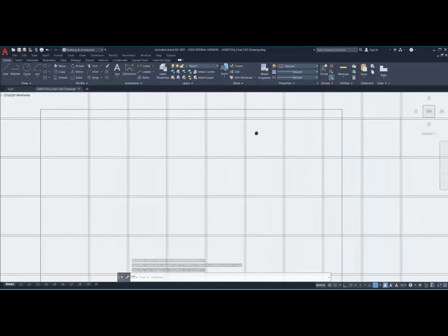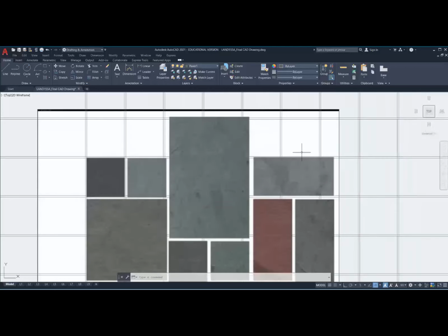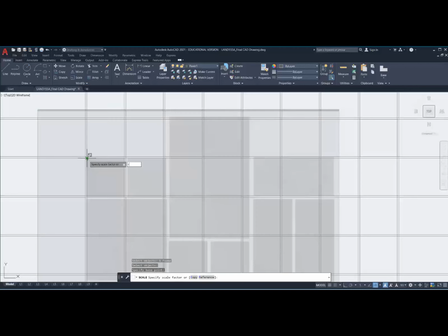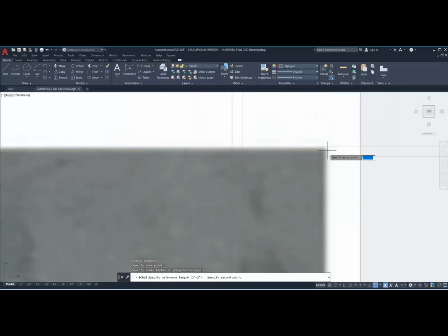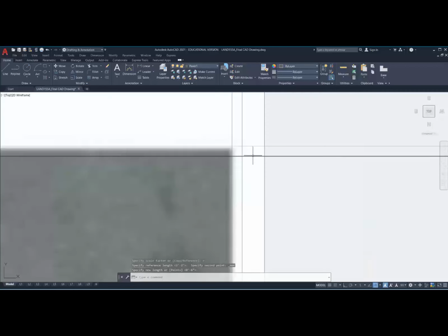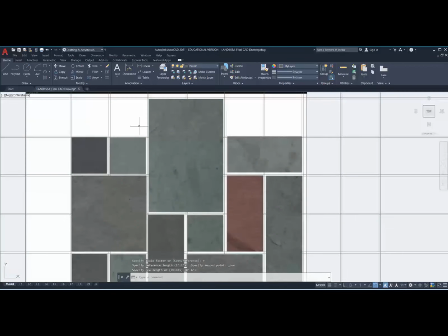So it's not too bad, but it's slightly out. By the time I get to the extreme right, it's way out. So let me rescale it one more time. Again, because it's a photograph, it's of poor quality and the accuracy level's way off. So I want to rescale that. I click on my base point, type in R and enter, and then my base point again, and click somewhere out here. I'm going to use none so it doesn't snap to any of the lines, and then click to snap onto a line.